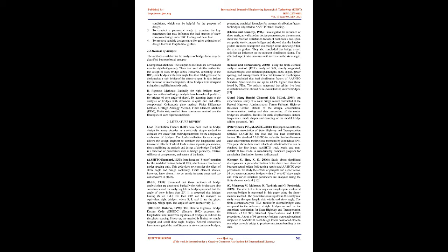1.1 Behavior of skew bridges. The behavior of a skew bridge is quite dissimilar from that of a straight bridge. In non-skewed bridges, the load path goes in a straight line towards the support in the direction of the span. The special characteristics of skewed deck slab are: dissimilarity in the direction of maximum bending moment across width, from near parallel to span at edge, to near orthogonal to abutment in the central region; growth of hogging moments in slab near obtuse corners; significant torsion of the deck.